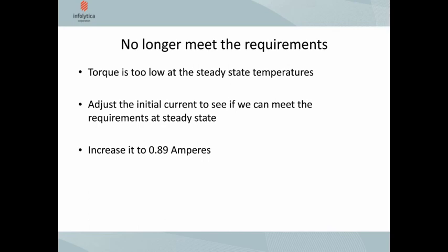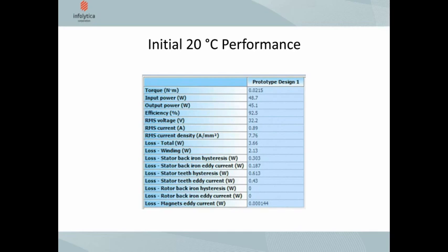And we're going to assess things at 20 degrees C. We see here that we have a little over 20. We have 21.5, in fact, millinewton meters. We have still maintained our under 8 amp per square millimeter constraint. We've got additional losses. We're going 3.66 instead of the 3 3/8.